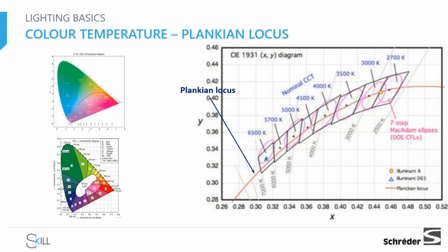Okay. We see here that we have the letter K, which is representing Kelvin, and we all know that Kelvin is something related to temperature. So if we are speaking about 3000 Kelvin, we are speaking about almost 3000 minus 273 to get something around 2730 degrees Celsius. And of course, we are not expecting that we have really a very high temperature inside the bulb. If we bring a thermocouple and we go for a 3000 Kelvin lamp, we will not find 3000 Kelvin temperature.